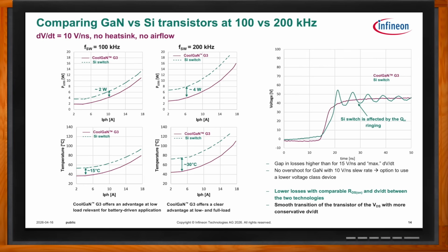Then it kind of abruptly heads up. And then you can see this change in slope right around 18, 19 nanoseconds. The slope changes. That's where the recovery is done and the diode lets go. And you get this classic ringing and overshoot associated with silicon diodes with reverse recovery. So, the ringing and overshoot, you can say, it's no big deal, but it can be because, number one, it's going to increase EMI, as I mentioned earlier, and the peak voltage is higher. Not a huge deal here, but it depends on your layout.